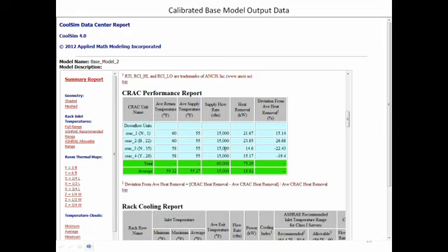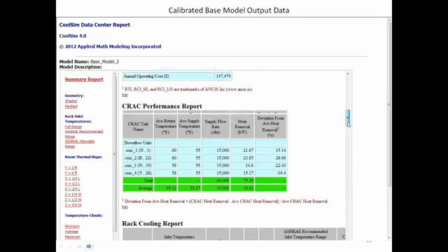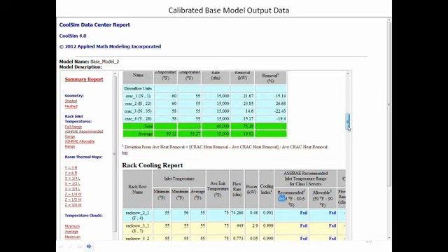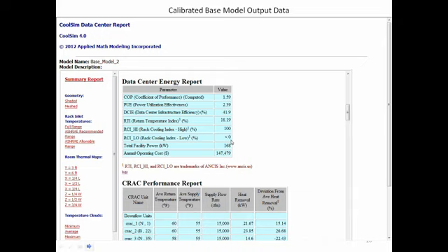By the way, the maintenance cost on this unit is going to be high too because it's cycling on and off. Can't figure out whether it should be on or off. It's underloaded. It's running way below its design point. They don't work well there, so maintenance is going to be high. Reliability is going to be impacted. And it's failing the ASHRAE spec with respect to cooling. It's too cold. The specification says 64.4. And we're running this thing down to 55, so we're below the spec. And that's why back in the energy report we have it less than 0. Actually, the calculation shows it as a negative number. We decided the best thing to do here is just say, yeah, it's 0 or less. Yeah. Forget about it. A couple other things we've done in CoolSim 4 which are kind of nice.